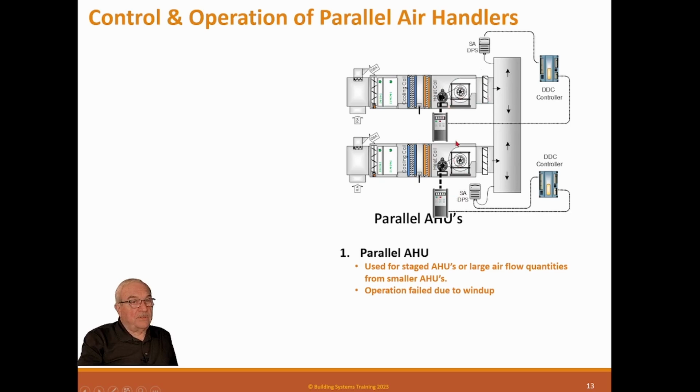What happens is, just think about it for a second. If this is pressure controlled, and all of a sudden this one sees first that this duct needs more air, it will speed this fan up. Well, as this starts to speed up, this one says, well, I need a little more, so it starts speeding up. But this one, if it speeds up faster, will finally make the pressure, and this one will just back down. It's, oh, I've already got pressure. I don't need pressure. It'll back down. And that discrepancy will eventually drive apart.